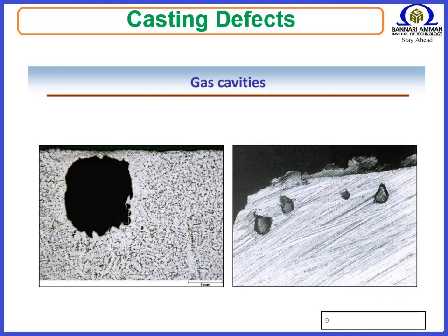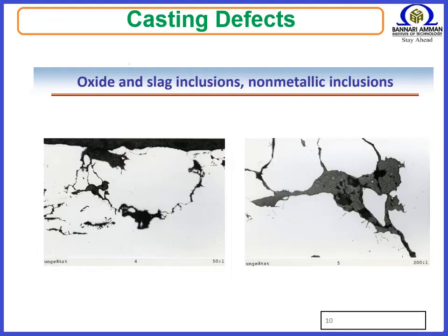Blowholes. When gases are entrapped on the surface of the casting due to solidifying metal, a rounded or oval cavity is formed, called blowholes. These defects are always present in the cope part of the mold. Causes: excessive moisture in the sand, low permeability of the sand, sand grains are too fine, too hard rammed sand.